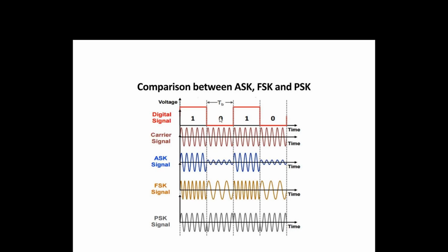If we receive the input 0, the frequency of our modulated signal is low. So we have a frequency modulated signal with constant amplitude. Here we don't change the amplitude of the carrier signal. Only the frequency of the carrier signal varies. That gives the result of frequency shift keying.